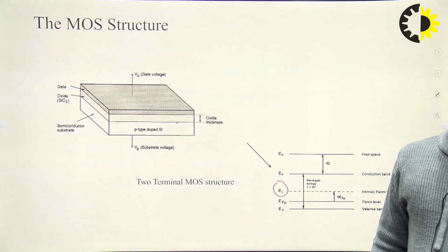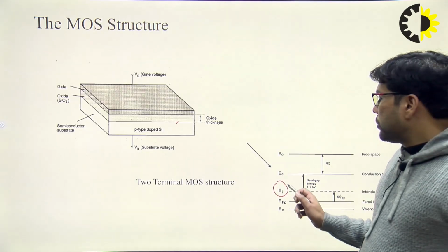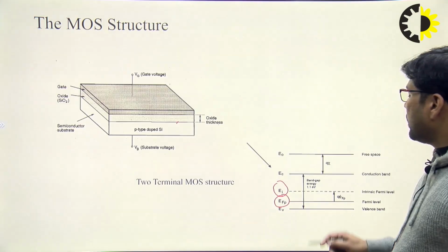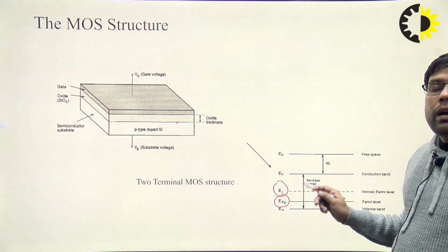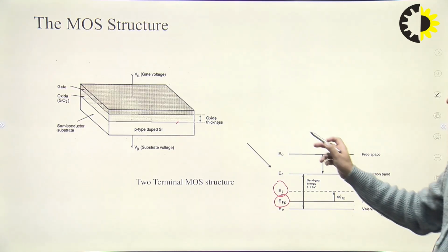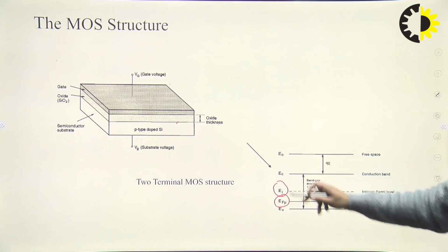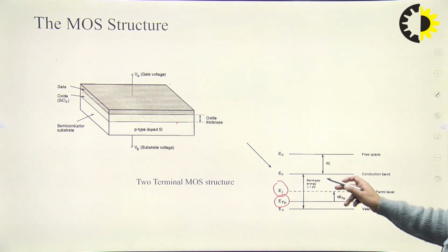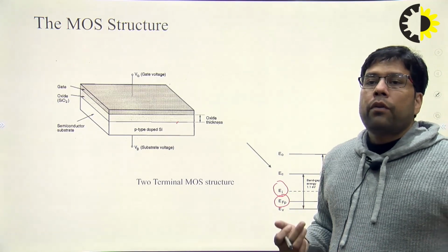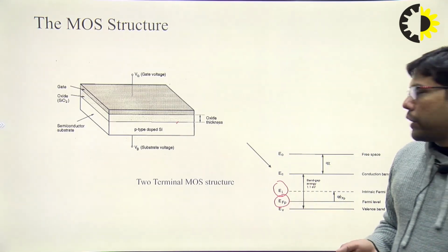That's why in the p-type semiconductor, the Fermi level lies just above the valence band. Here you can see for the p-type semiconductor we have marked the Fermi level just above the valence band, right? So this is the energy band diagram of the p-type semiconductor, and we have an energy band gap of 1.1 electron volt, because the forbidden gap for silicon material is always 1.11 electron volt.